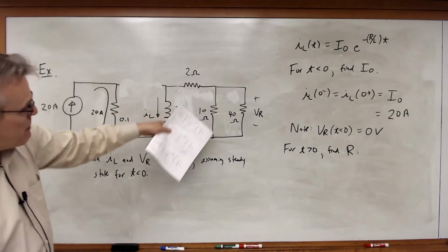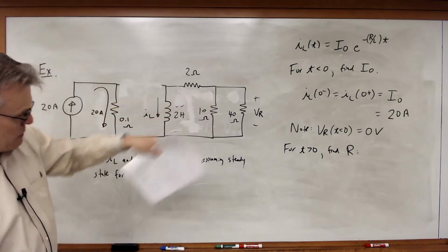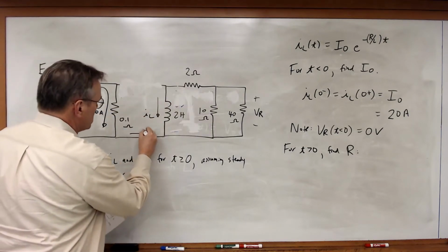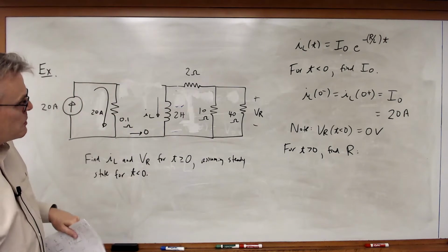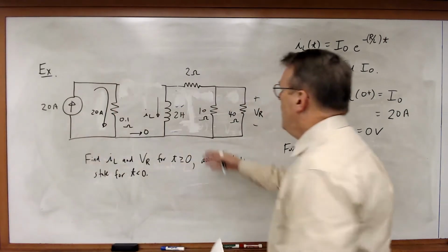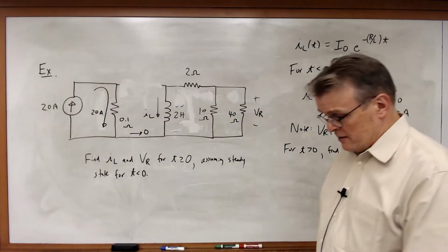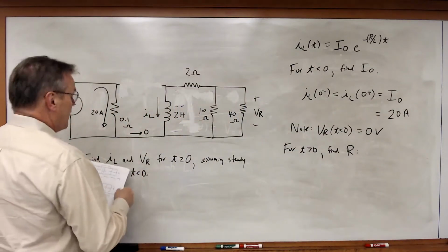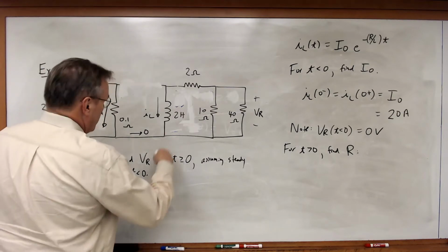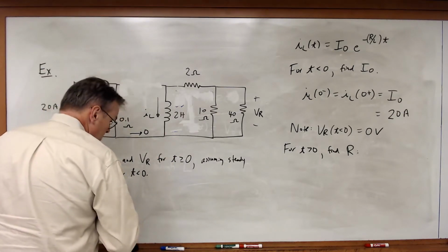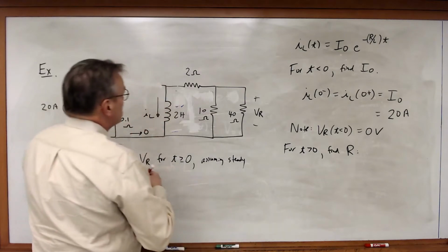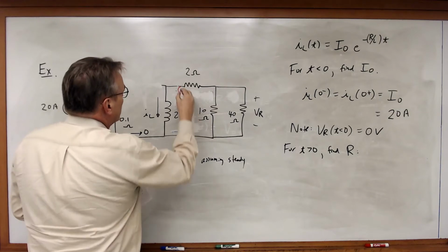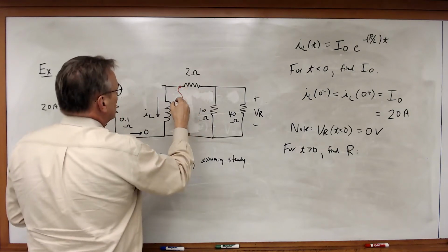So everything that's going to happen is going to happen between this inductor and these resistors on the other side, because I know that the current through here has got to be 0 just by KCL. So given this, what is the resistance across this inductor? Well, the resistance across that inductor must be the resistance between these 2 points across the inductor.